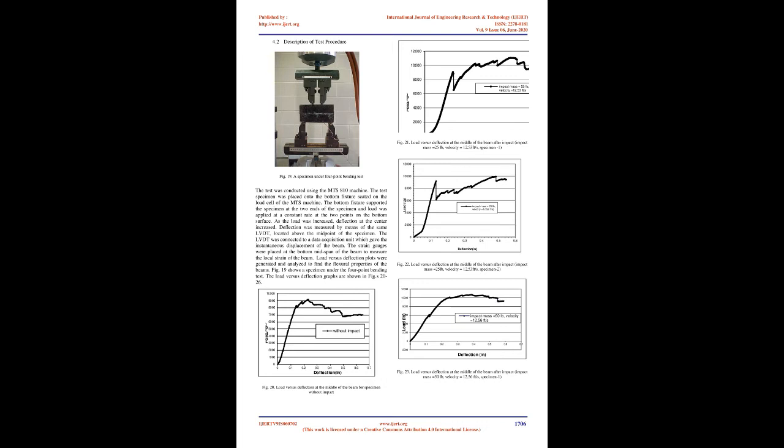The peak load, the initiation energy and the propagation energy for different impact tests are summarized in Table 8. It is found that, in general, the initiation energy decreases and the propagation energy increases as the hammer weight increases. This suggests that, as the hammer weight increases, the damage is extended to a larger area. More material is involved and affected by damage with a higher hammer weight.